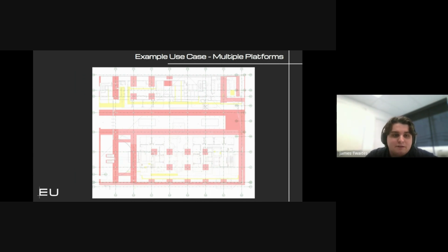So on this drawing, this is the same slab plan. And now red is showing slab bands, which are full of rebar, and yellow is showing cast-in electrical duct banks, which I'm told you should not core through. In the area that I showed a moment ago, this is from that same spot in the green there. This looks like a pretty promising area to scan for new core locations. There will be rebar and small conduits that we'll need to scan for and core around. But we can be confident that in a location like this, we will be able to find a location that will work.